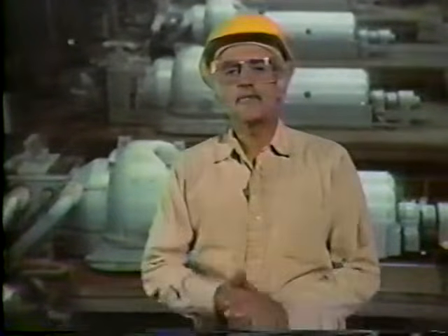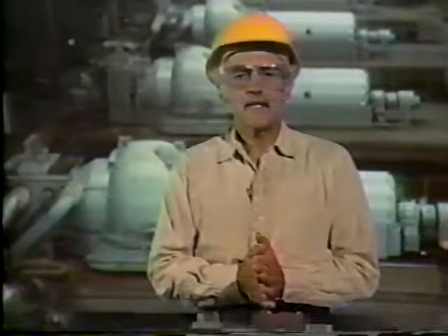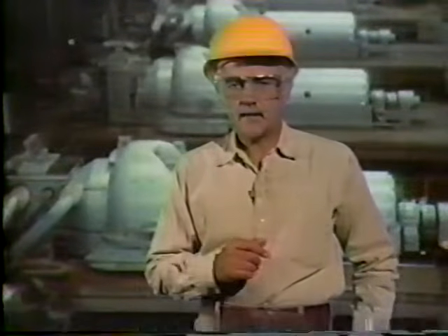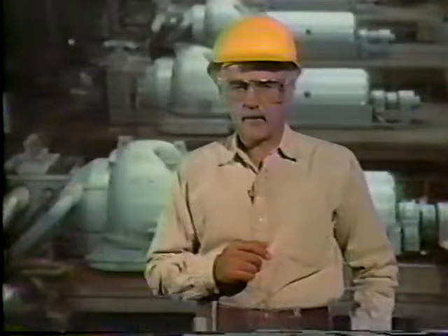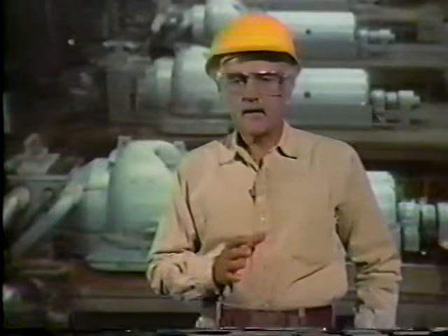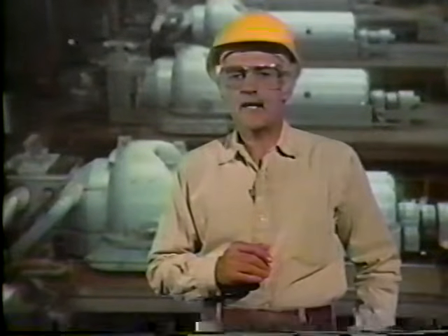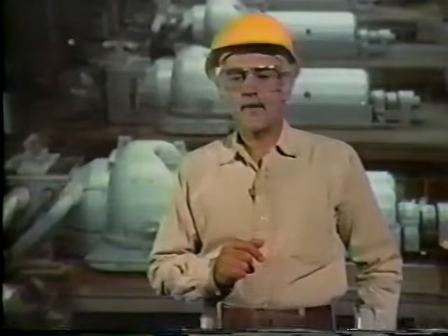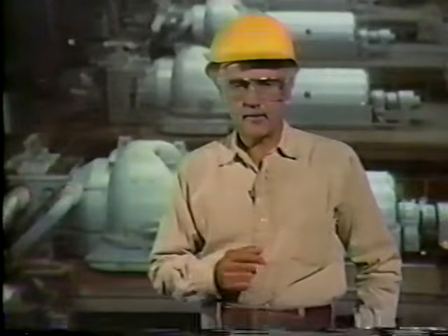One of the most important uses of oil in a turbine is for bearing lubrication. Bearing lubrication supports the turbine rotor, allowing it to rotate while preventing metal-to-metal contact between the stationary and moving parts. In addition, the lubricating oil carries away heat built up in the bearings. Lube oil is also used for hydraulic control systems in some turbines.